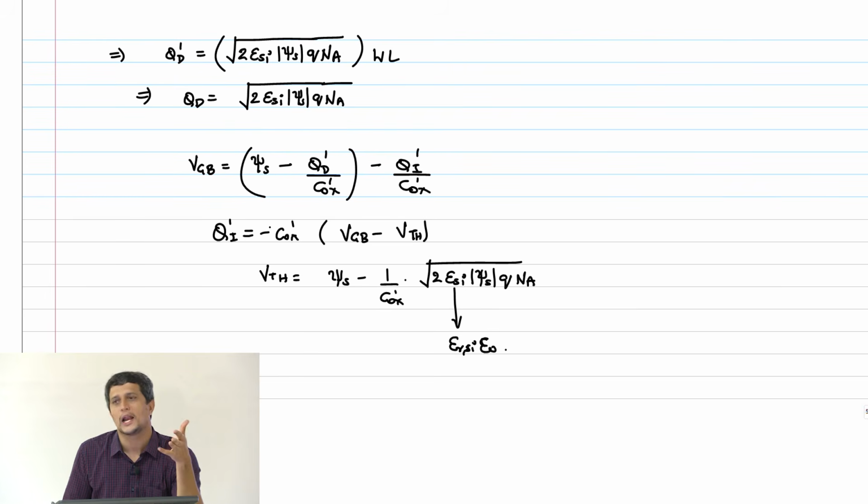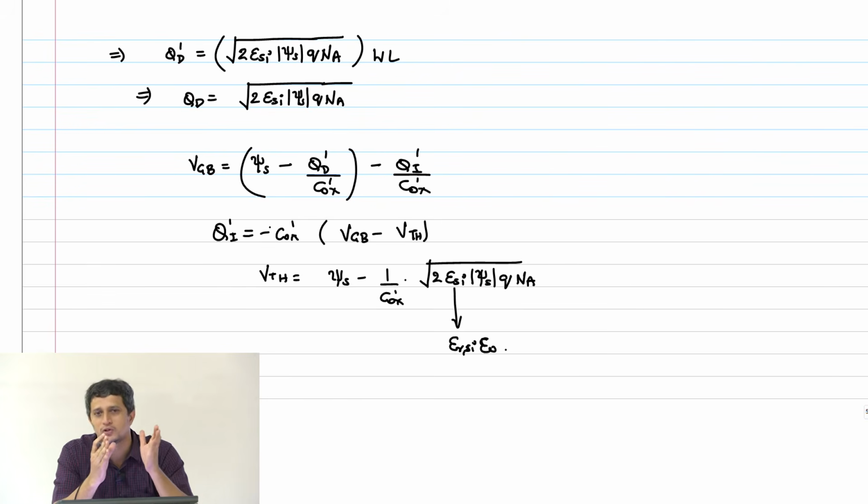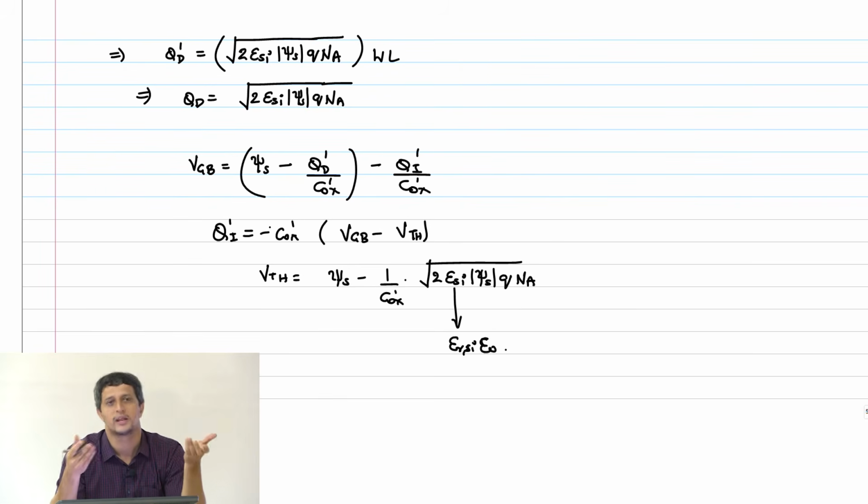In order to do that, I first need to deplete part of my body or part of the substrate, and that work that the gate voltage has to do in order to invert the channel is basically called the threshold voltage. So, even if you apply a large potential, it is only VGS minus the threshold voltage that is actually going to be available for you in order to create more inversion charge and thereby increase the current from there on.